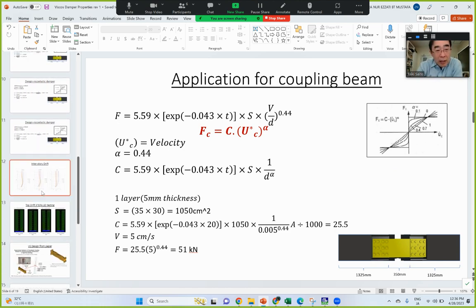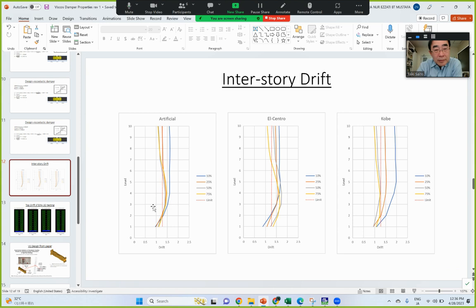As you mentioned, I think the strategy doesn't work. So I tried to run a time history analysis, but I think the story drift is not adequate for the target drift of 1.28 centimeters. This is the result of the time history, sensei. But the artificial time history also doesn't work, right? Yes, I think it doesn't work. How did you get this time history? I just put it here.